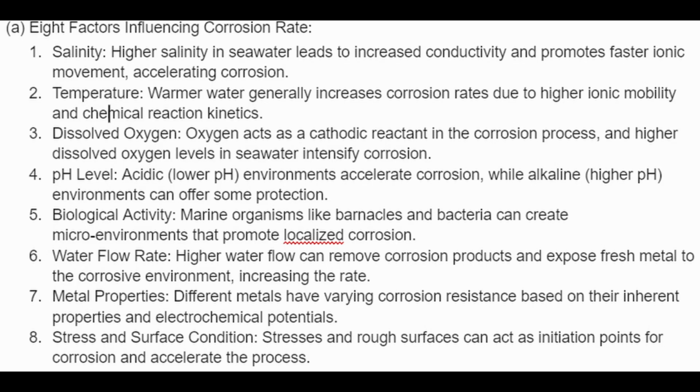A. 8 factors influencing corrosion rate. 1. Salinity. Higher salinity in seawater leads to increased conductivity and promotes faster ionic movement, accelerating corrosion. 2. Temperature. Warmer water generally increases corrosion rates due to higher ionic mobility and chemical reaction kinetics.